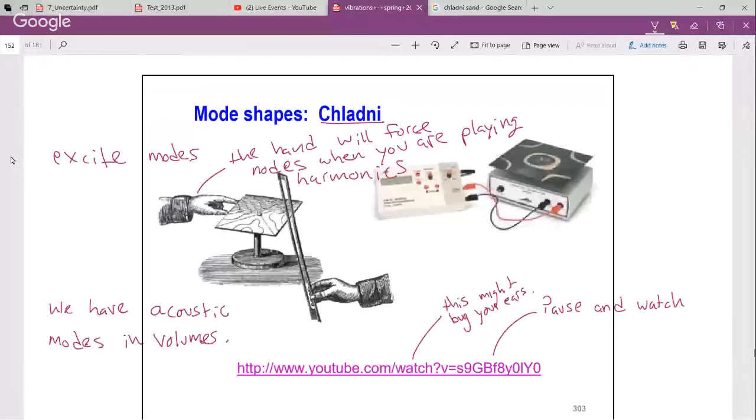If you're making excessive noise and code enforcement comes, whether you're a company, an industry, or a resident, they'll take a measurement, but they'll use A weighting because they want to mimic what your ear hears.